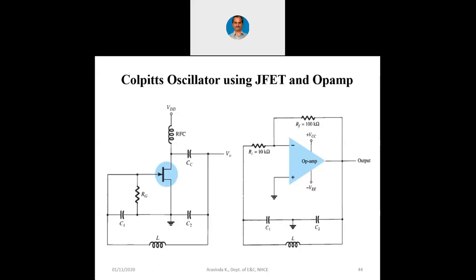Again, that value 1000 will not be fixed as such. It will be different from amplifier to amplifier whenever op-amp is manufactured, again because of the beta of the transistors. So it is not at all advisable to use operational amplifier in the open loop gain. Whenever we use op-amp in the open loop configuration, we use it as a comparator and not as an amplifier.